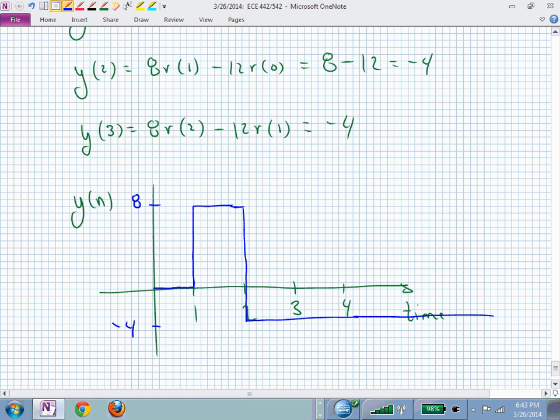Is this an acceptable response? You'll have to decide. But what did we do? We hit this system with a 1. But initially, what was our system behavior going to do? What was G of z? Remember you told me? It was unstable. So it was just going to go unbounded if we didn't do anything. At least this is a bounded response.